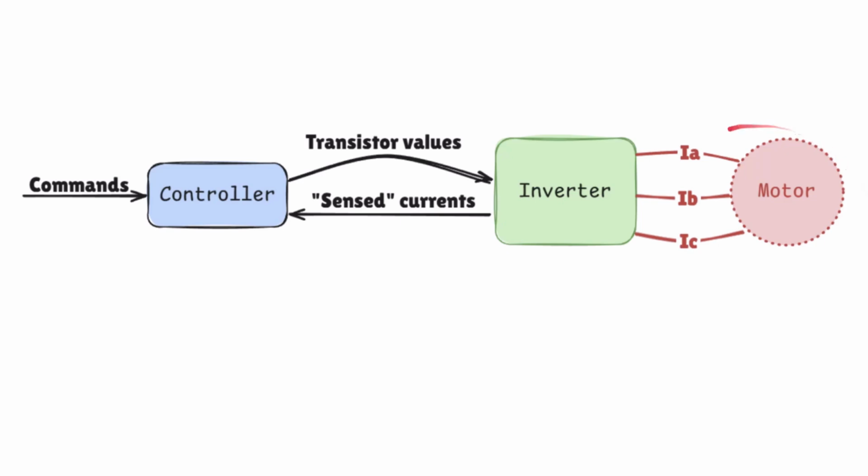Okay, so in addition to the simulated motor, I also wanted to simulate the control side. So we have a controller, which is the brains of the operation. Based on the desired commands, it runs all the calculations and gets the phase currents, which we find through solving differential equations. By the way, there's no position sensor right now since the speed and angle are calculated by the simulation. The controller commands the inverter, which is the part that actually sets the voltage on the phase terminals.